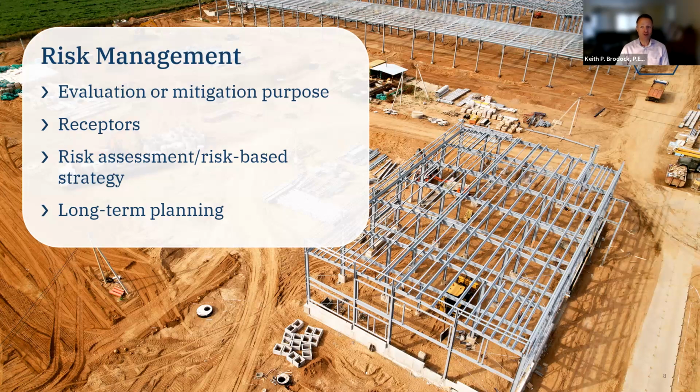And sometimes it's important too to consider what's the zoning for that property. So while it may not be a daycare right now, is there a chance it could be a daycare in the future? And you want to have that conversation with the stakeholders. If this gets sold, is there an action that we should take now so that it's easier to make an adjustment for, let's say, a mitigation system in the future if there's a more intensive use, such as a daycare, where there's more sensitive receptors? Think about it up front and do a little extra homework to make sure that that conceptual site model is robust.